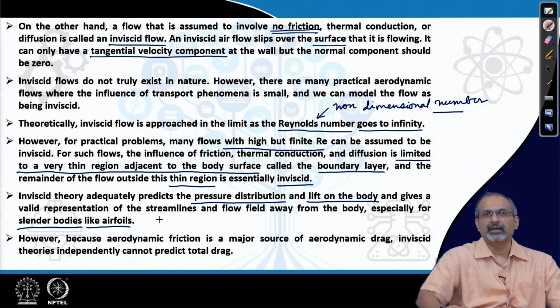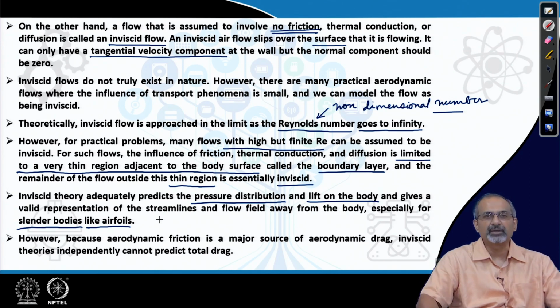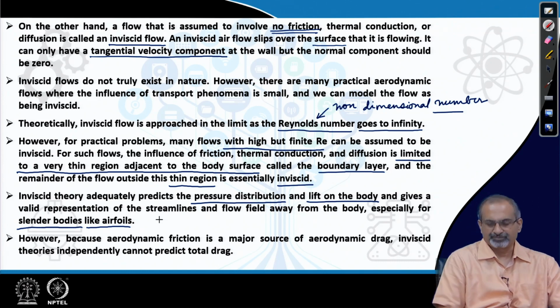However, as we have seen, at high angles of attack the flow can separate and viscous effects can then dominate the flow. In such a case, it becomes very difficult for inviscid theories to predict the pressure distribution well. Neither can it predict the aerodynamic drag, because inviscid theory cannot account for drag effects.